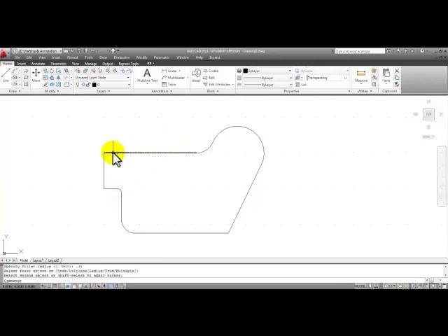All of these objects are individual objects within AutoCAD. To turn them all into one object so that we can easily offset this continuous line or polyline, we're going to use the p-edit command or polyline edit. It's underneath the modify panel title. Click right on the word modify and look for the icon that has the small pencil, the first small pencil. Notice that the type in at the command line is p-edit. Go ahead and start that command.